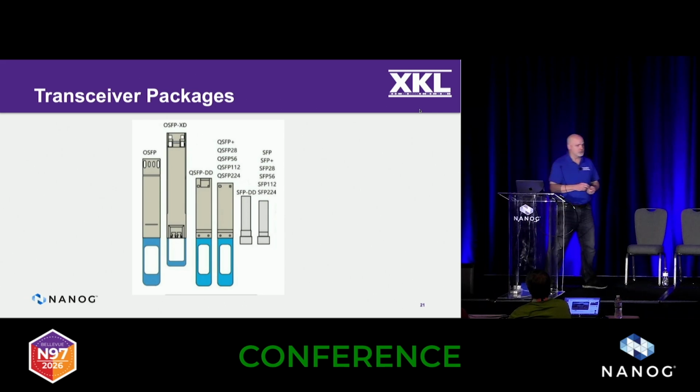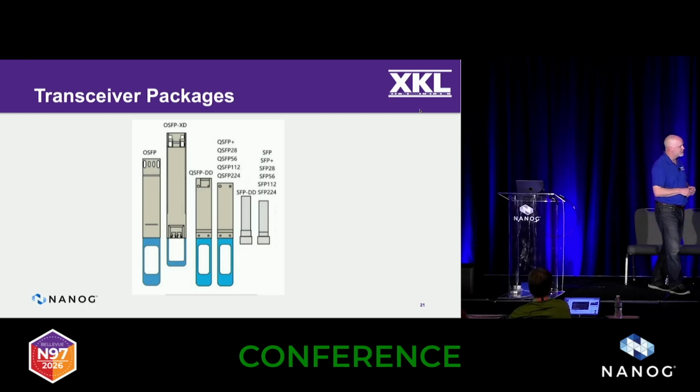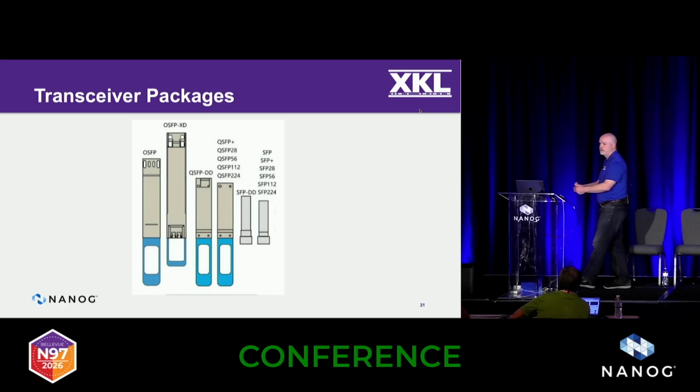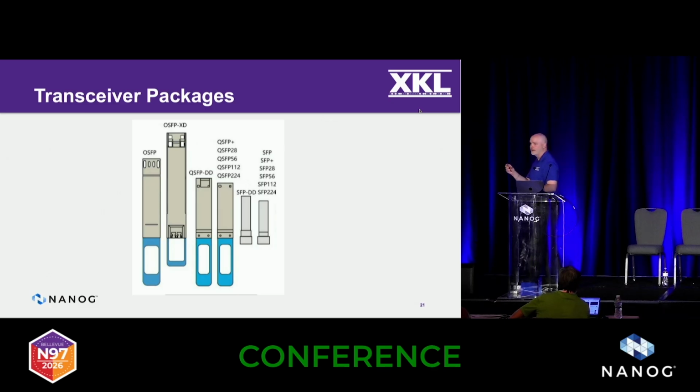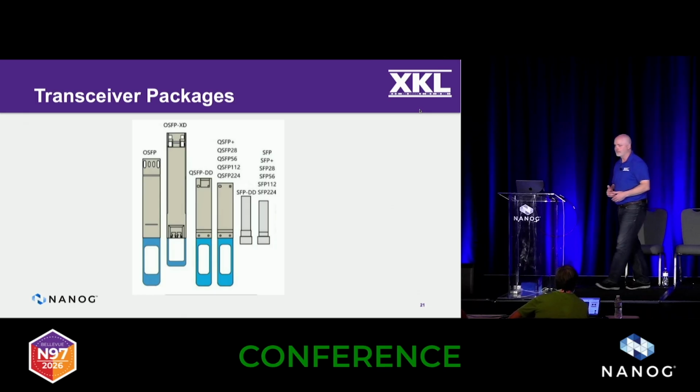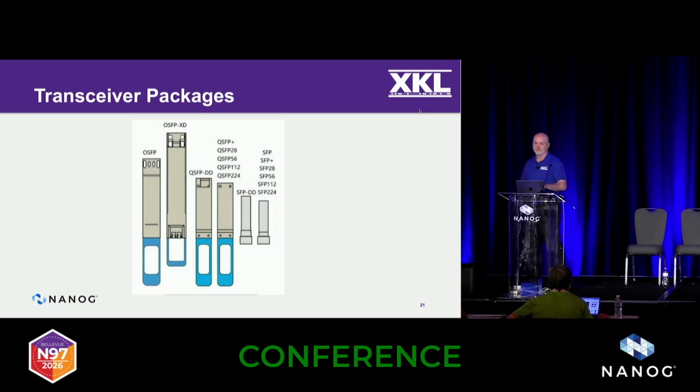This graphic is just to show you sort of physical stuff, right? What's the basic size of these things? OSFP is a little bit bigger than the QSFP DD, so you get a little bit better heat dissipation out of that. But you know, the size is significantly different. And this doesn't necessarily count like what's inside the device that's hosting it. You've got a bunch sticking out, right? So that door on your cabinet doesn't quite close anymore with all the advantages of the new technology of putting erbium doped fiber amplifiers inside the transceiver. So they've stolen some of the space out front. But this is the envelope that they have to fit it in.